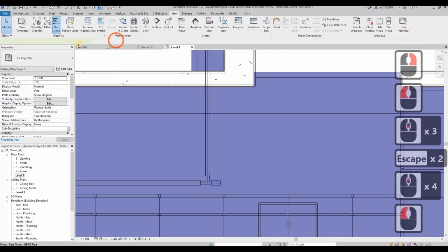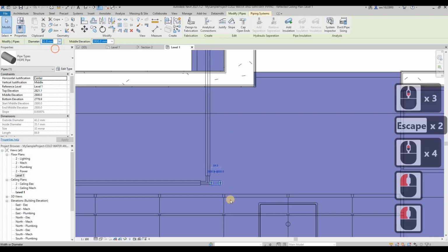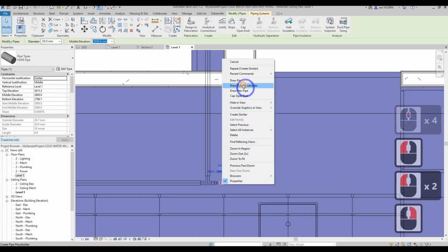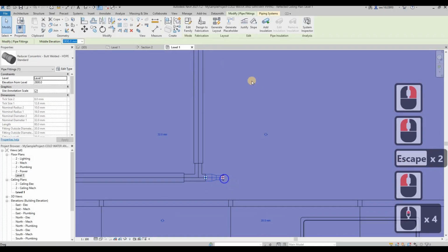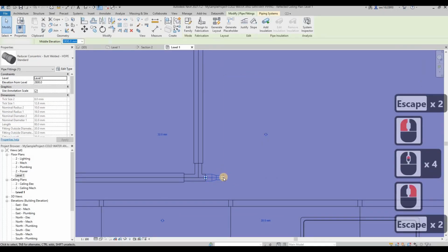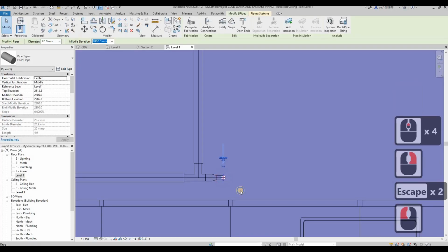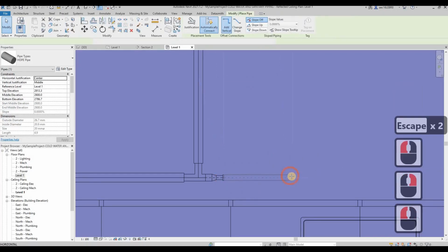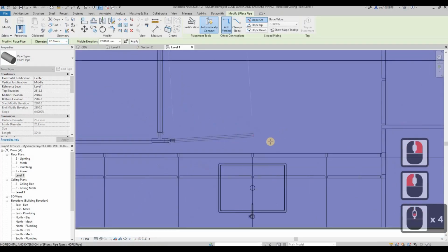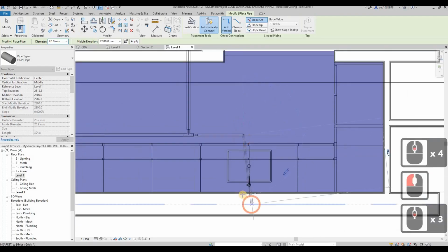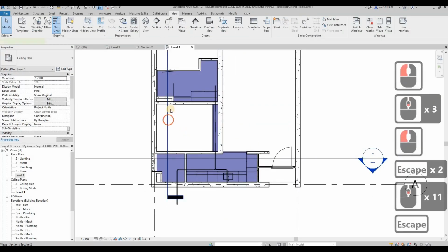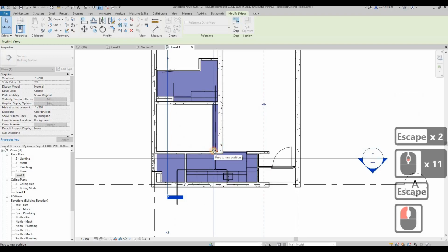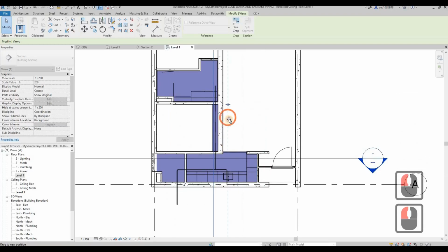Most likely this will be a 20 mm pipe. Just draw a pipe. Start to draw pipe, 20 mm. Then you go down to your sink key. Of course, you need your section view to be able to check where the pipe is supposed to be dropped down.